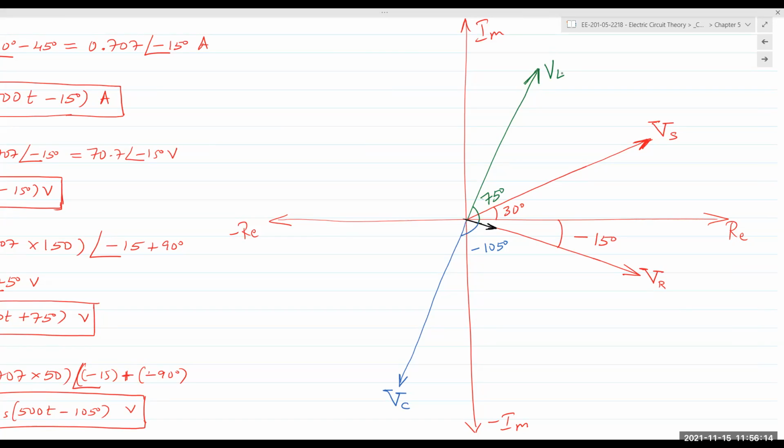But again, the phasor diagram without complicating the relationships: first, find the angle. Once you find the angle, you just plot it along that angle line, and then just mark the length. That's it. That's the phasor diagram. And if you wanted to plot KVL, we would do it by taking all of the angles into account. So it would be VR, then VC, and then VL, and then VS would be satisfied. Without taking the angles into account, the magnitudes would not add up.